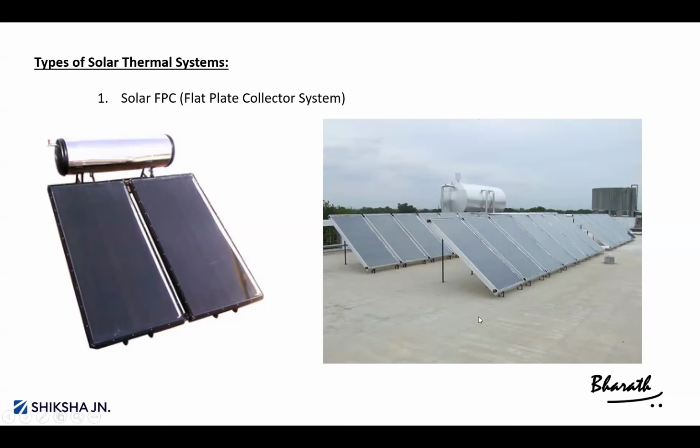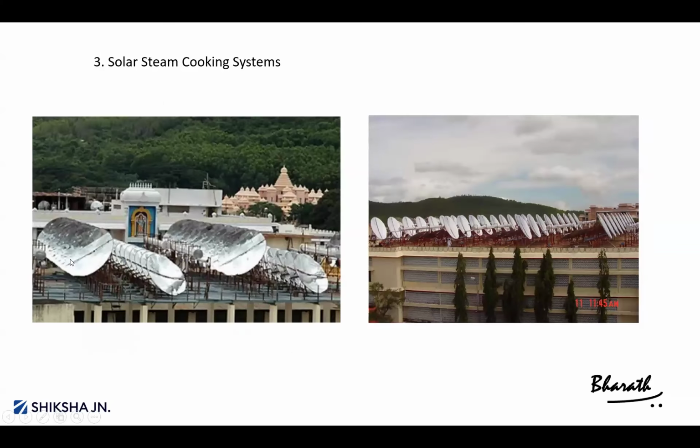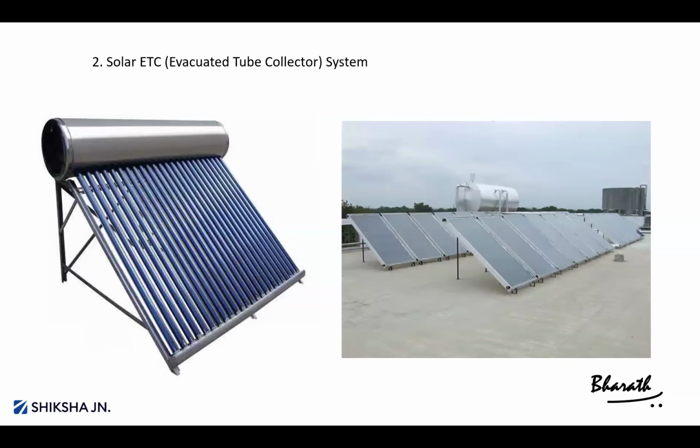So here the water will circulate to these plates, and we can use the storage tank. So from here we can take the outputs to our utility points. And this is another model, ETC, evacuated tube collector system. Here also the same, water will circulate to here.